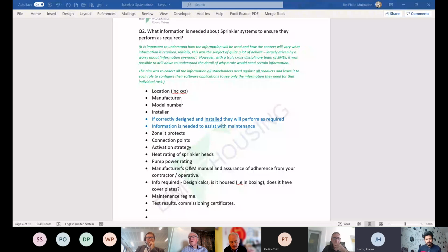One thing that the Germans do, we don't yet, is a 25-year inspection, a very detailed one. We can do some of that here too. You take samples of sprinklers and have them tested to see if they still function properly. Obviously, those ones would have to be replaced. They also take an endoscope and look inside the pipe to see if it looks all right. Various things like that can be done. A lot of these residential systems would use CPVC pipe, which doesn't really corrode, so you haven't got so much of a problem there.